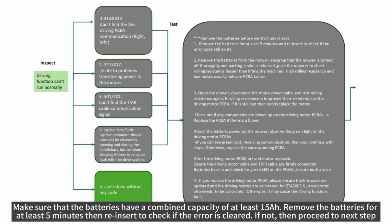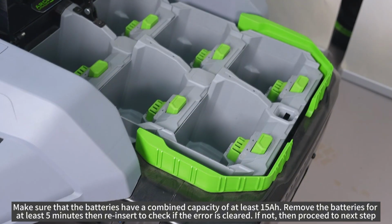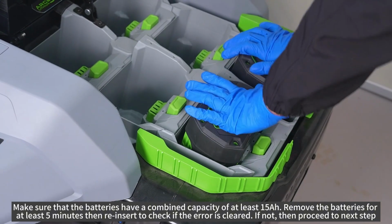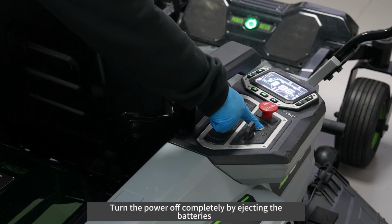Make sure that the batteries have a combined capacity of at least 15 ampere-hours. Remove the batteries for at least 5 minutes, then reinsert to check if the error is cleared. If not, then proceed to next step. Turn the power off completely by ejecting the batteries.